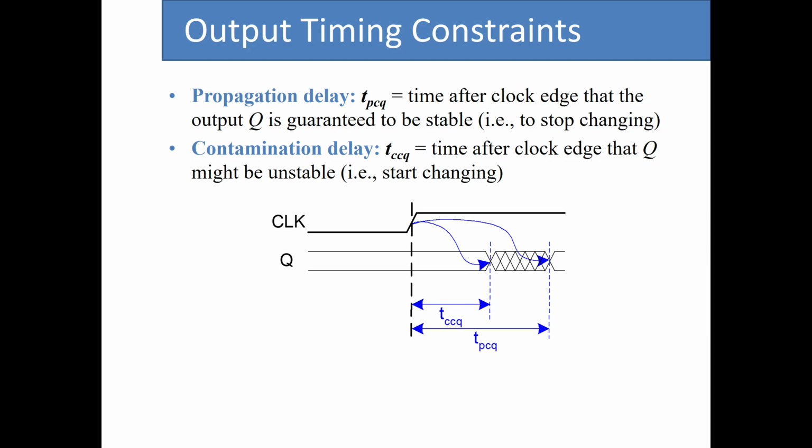That is why we have delays in logic circuits. But we said the amount of delay is not fixed for any combinational logic circuit. It depends on how many gates a signal has to go through to get from the input to the output. It depends on whether the circuit is kept in a cold place or in a hot place, and so many other conditions that can affect the delay of the combinational logic circuit.